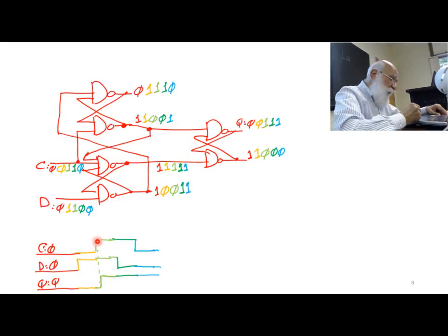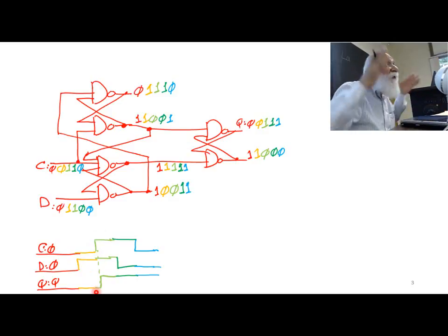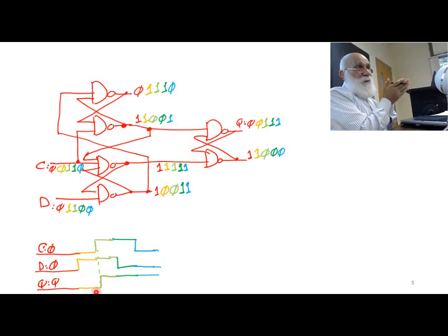When the clock goes from 0 to 1, the value of D goes into the output right there. And then the clock being 1 doesn't cause any changes. Even if D goes 0, 1, 0, 1, the output is 1 already.